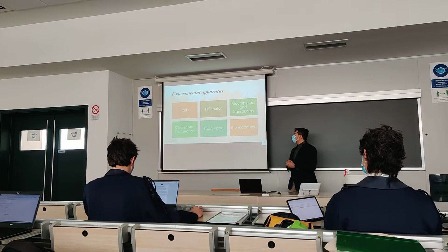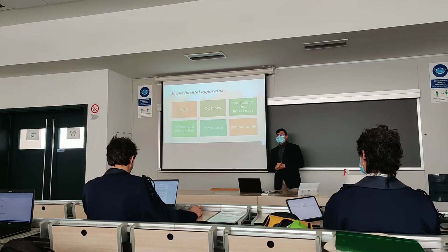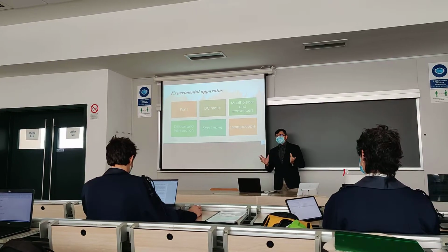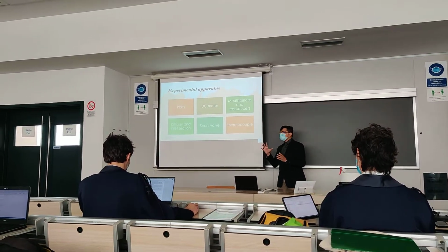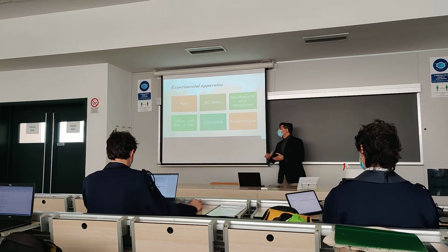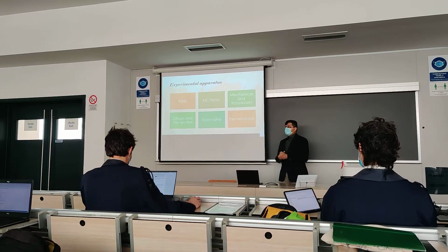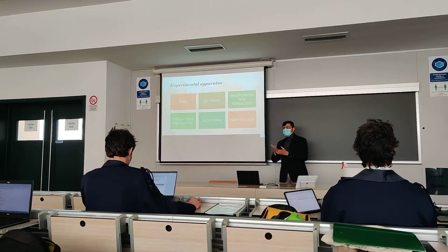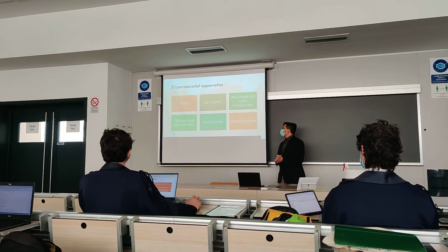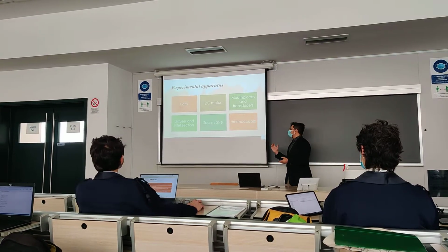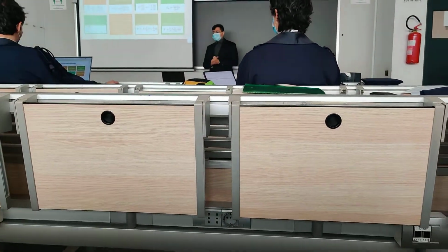And then comes the diffuser and inlet section, which is the area of interest. The diffuser is where the entire thing is concentrated, where we are going to concentrate on the boundary layer. And then comes the scanning valve. The scanning valve is an interface where the pressure readings are converted digitally, and we can measure them through the lab software. And next is the thermocouple. A thermocouple is a sensor which is used to measure temperature.